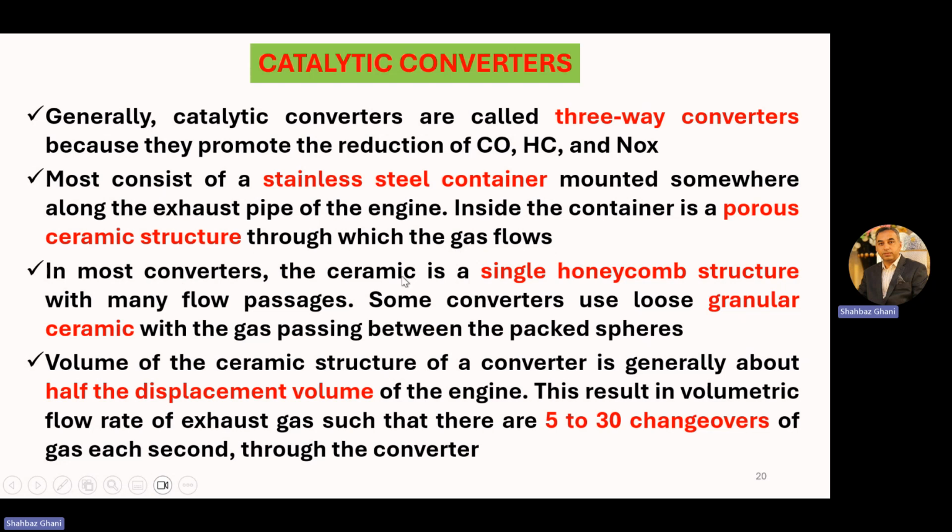In most converters, the ceramic structure is a single honeycomb structure with many flow passages. Some converters use loose granule ceramics with the gas passing between the packed spheres, instead of the single honeycomb structure.